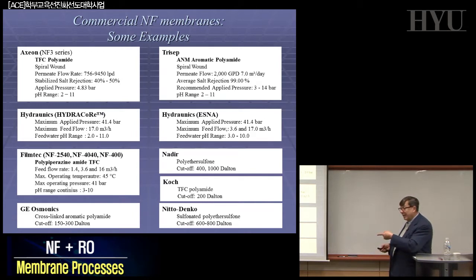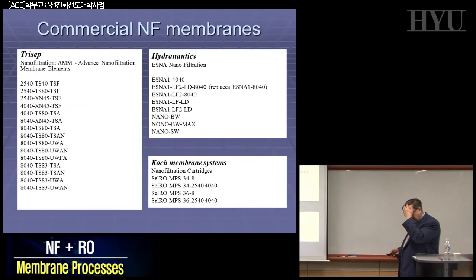And 15 years from now, in this area, there will be new membranes. Not very much in ultrafiltration, not very much in reverse osmosis, but in this area, yes. And particularly for species working not in water, but in organic solvents. If you have any polymer that you know is stable in some organic solvents and not yet utilized as a membrane, check, because that can be a field of interest.